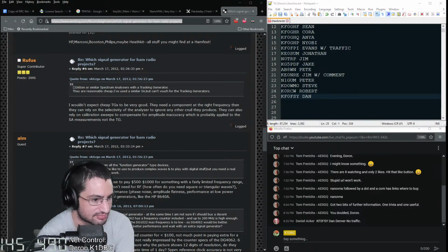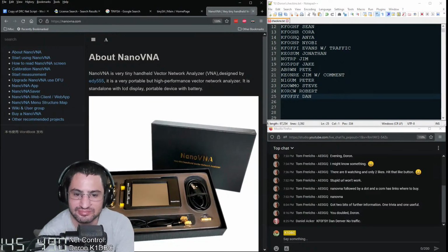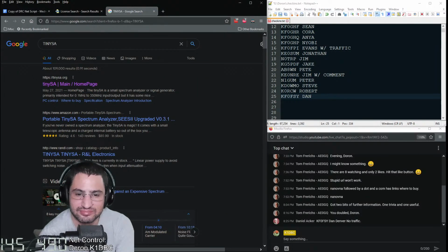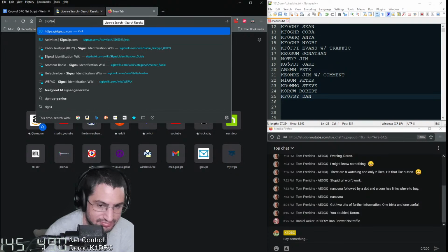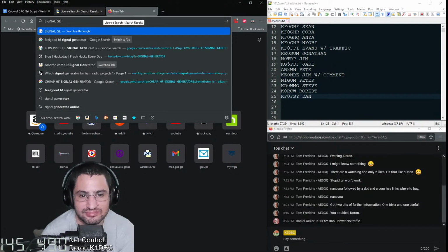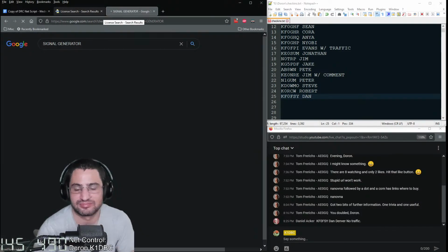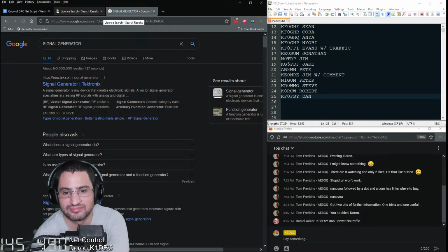Of course, that may not exist, and it may simply be easier to use an inexpensive noise generator with something like the tinySA, which unfortunately doesn't have a tracking generator. So you could use a noise generator that goes up to 1.5 gigahertz and then simply average it out. That may be the way to go if I want to scan a filter, a bandpass filter for example, and see what it's actually doing. So that was the goal.